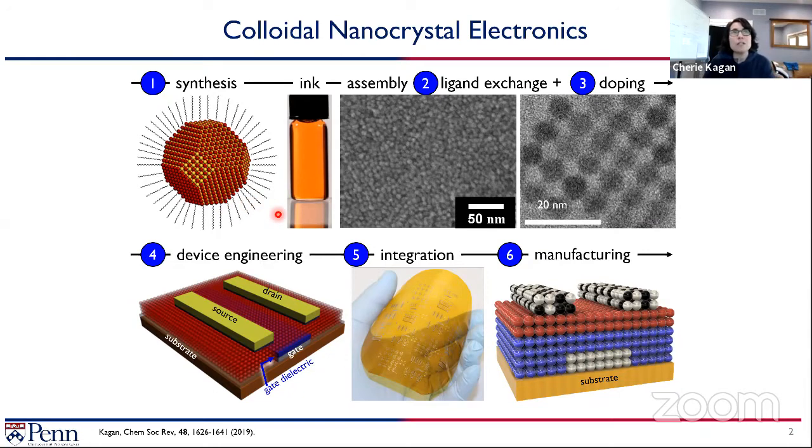You saw this also in Professor Loy's presentation, lots of vials of dispersed quantum dots. Then we use similar techniques today. I won't focus so much on the assembly techniques, where we'll mostly use things like spin coating. But what I will focus on, from an electronics perspective, is the importance of things like ligand exchange and approaches for doping. I think this came out in the questions from Professor Loy, with examples where we have glassy or locally ordered assemblies of quantum dots.